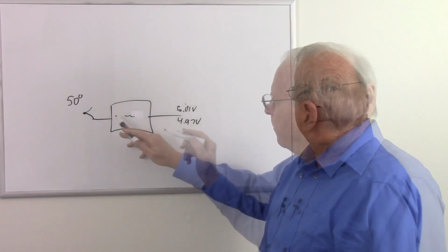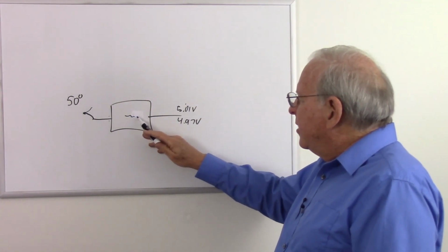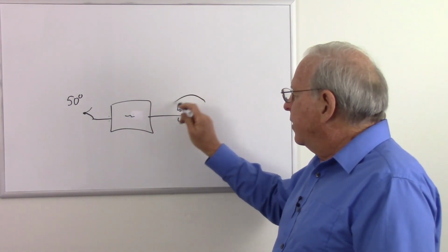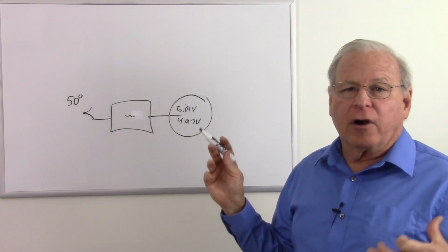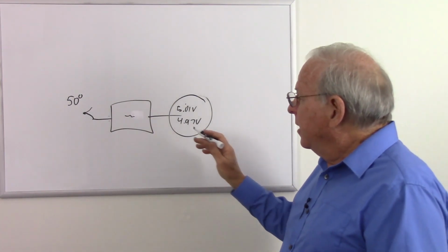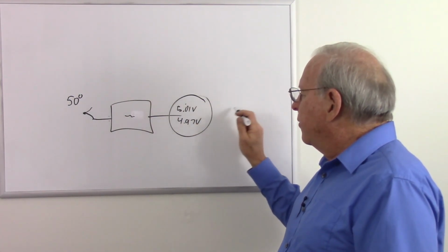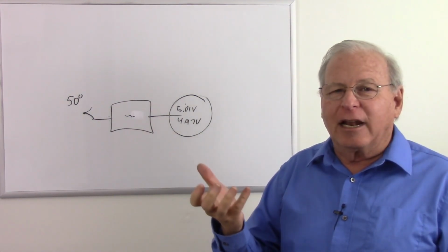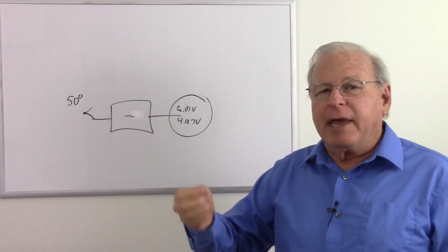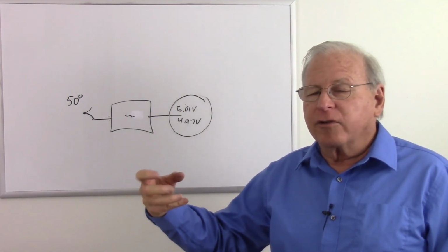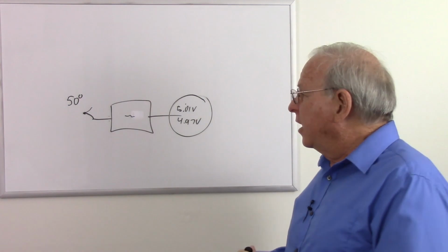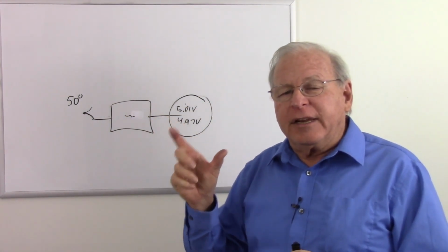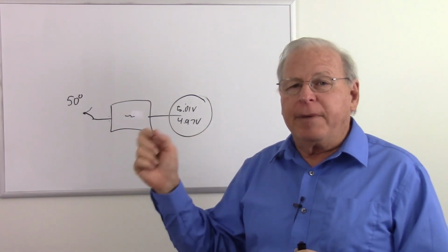As a matter of fact, as the temperature changes, and who knows what might change over time, these numbers might change. The problem we have here is integrity of the data. It might get changed from one side to the other. If the changes are small, no problem. But let's say we have to go through another circuit and another circuit and another circuit, or especially when we have analog systems that make copies, like analog recordings. Every time we make a new recording, we introduce errors, and it gets worse and worse as we go down the line. So analog systems have trouble with integrity from one end to the other and repeatability.